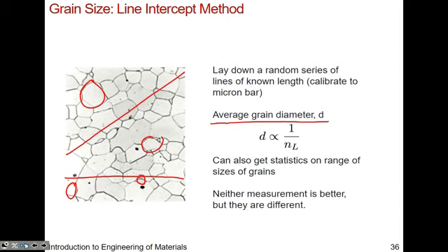Yes, I would say this is low res. The way these micrographs are taken, it's just by the reflection of the light. So if there are void spaces in between the atoms, they reflect differently. That's how you get these sizes. So my guess is there was some random void there that reflected the light differently in the optical microscope.